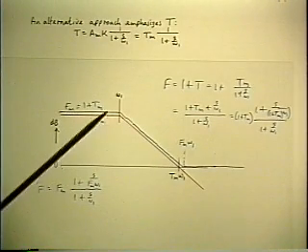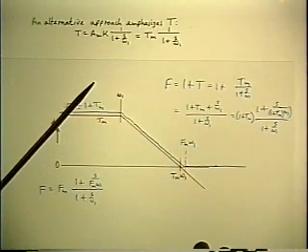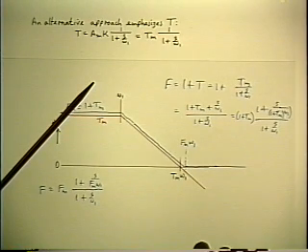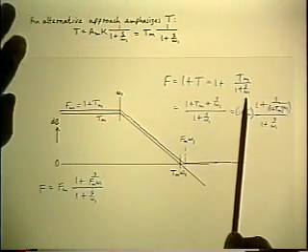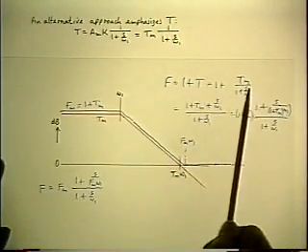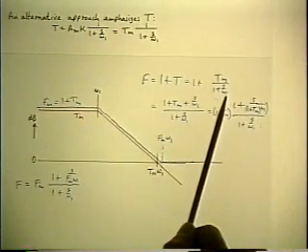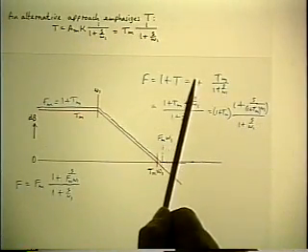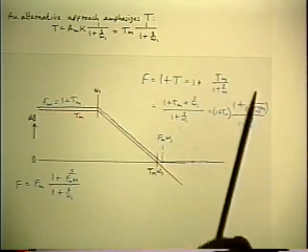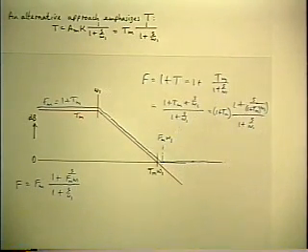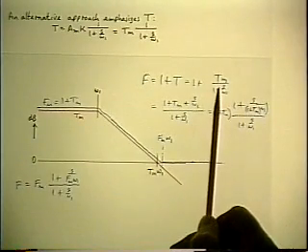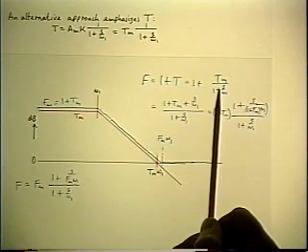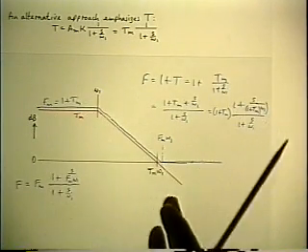Suppose you had an AC coupled system and the loop gain drops off at the bottom end as well. That's another pole. So the formula for T would have two poles. So how do you find F algebraically in that case? You have to cross multiply. You have to multiply the two poles together, add a constant. That gives you a new quadratic to factor. Well, you can handle that all right now if you use the new version of the quadratic, but still it's noticeably more work. The graphical method would remain just as easy.